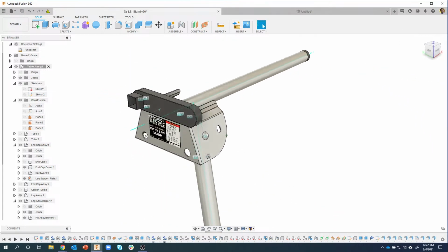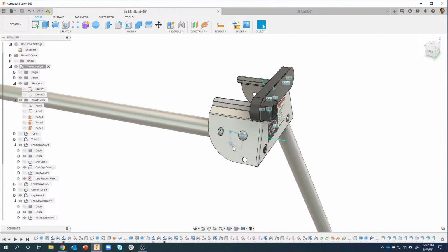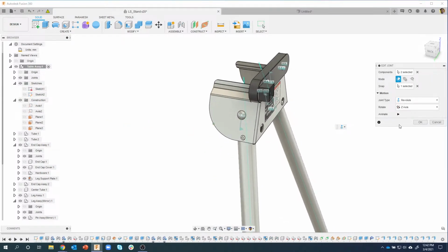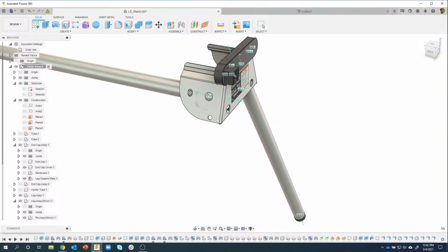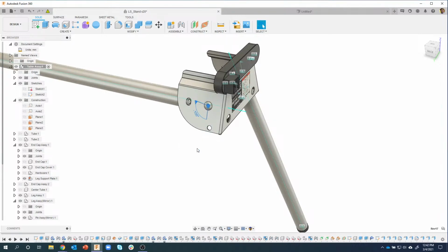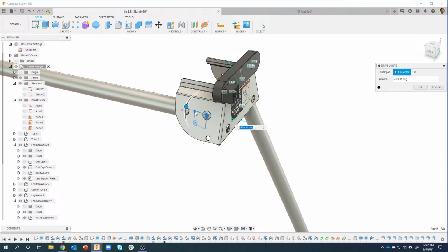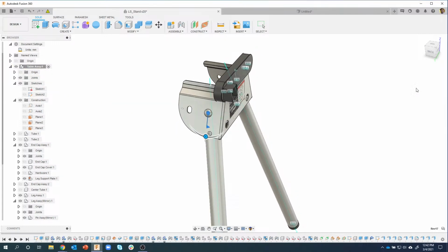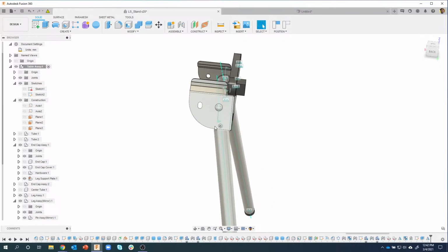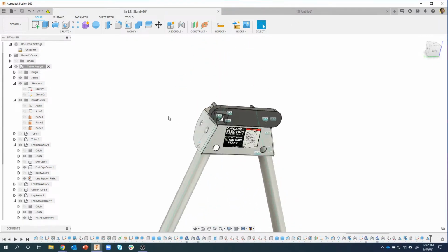Okay. Let's edit this joint here. Or I'm sorry, maybe I need to edit my joint limits. Maybe. Okay. Oh, I'm sorry, I'm doing the wrong command. I want to do drive joints. Let's go drive joints, that guy. It's set to -100. Let's set it back to 0. I'll say OK. Capture that position. So I just wanted to return that back to its original location.